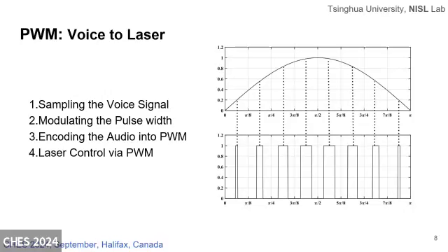So how do we get accurate voice signal sampling? According to Nyquist, it is essential to capture the full information of the audio. After sampling, the voice signal is converted to the PWM signal, and the variations in the pulse width follow the audio amplitude changes. Such conversion technology, particularly uses the unipolar PWM signal as shown in the figure.